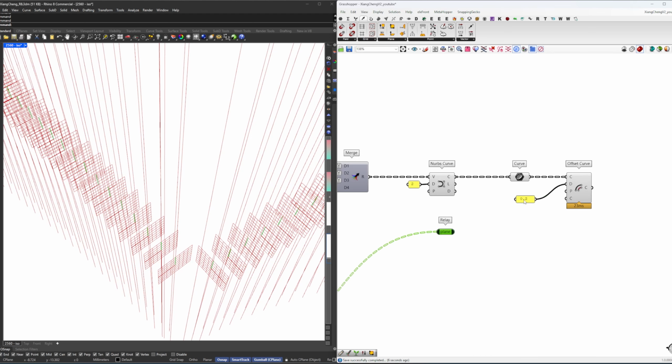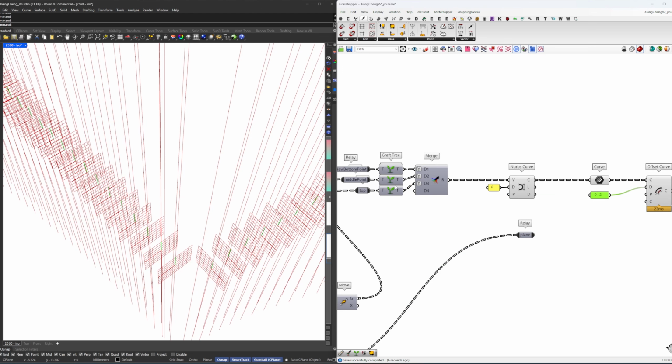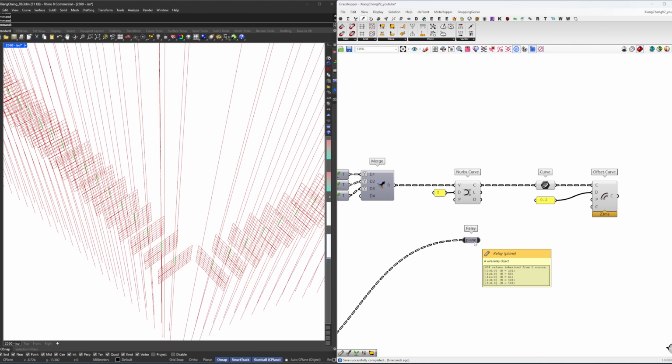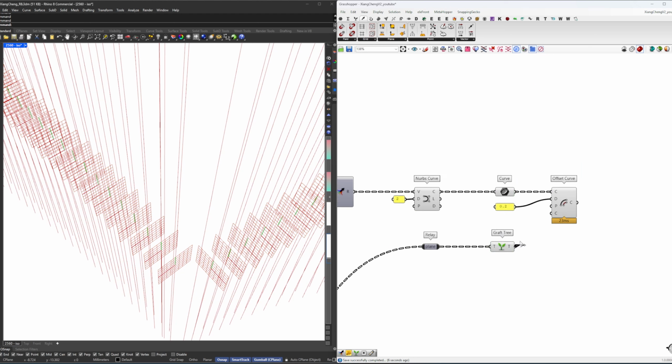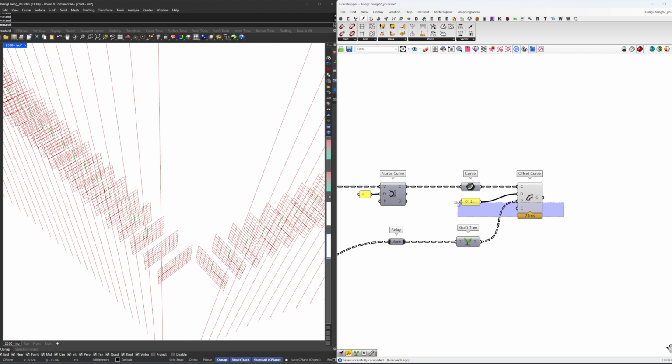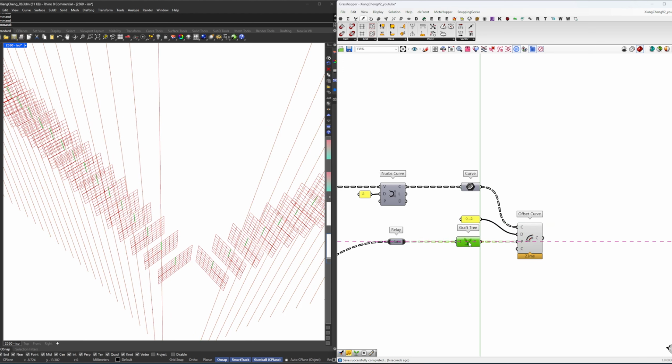One thing to mention here is we've grafted all our frames, right? So the data branches, we had like 404 curves. And here it's still the old data structure. So let's also graft this. And then bring it towards the plane. Yeah, and what you will see now, oh, this value is a bit hidden now.